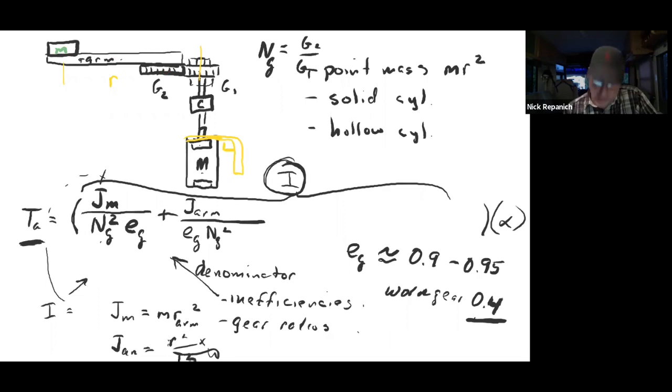So go back and look at the drawing. Should those have the same denominator? They're different inertia values, but the fact that they have the same denominator means that, yeah, they both got reduced by the same gear ratio, and they both are going through that same inefficiency. And since they could have been welded together anyway, yeah, that makes sense. Okay, so I wouldn't really look ahead. The first pass through, I would end up with 7 terms. Later on you can put those two, the mass and that, in the same term, but let's not do that for now.